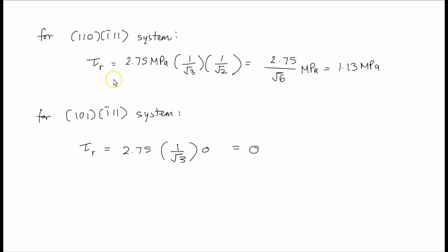But we may experience slip if it's sufficient enough. Okay, there's no information given here saying that this is higher than the critical shear stress required to cause slip. But this is how we can resolve a shear stress for a slip system.